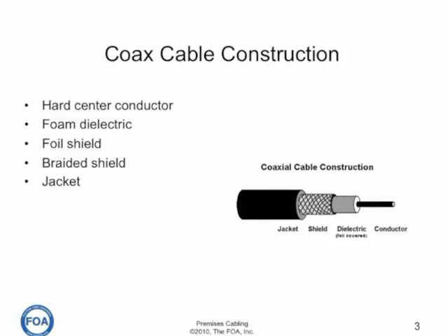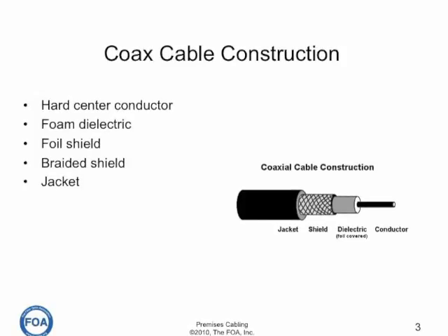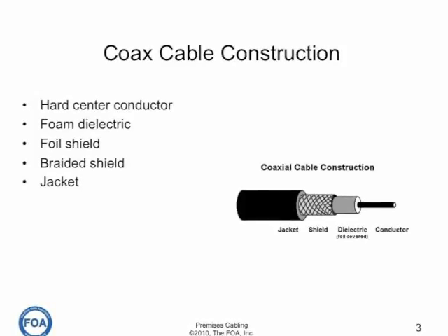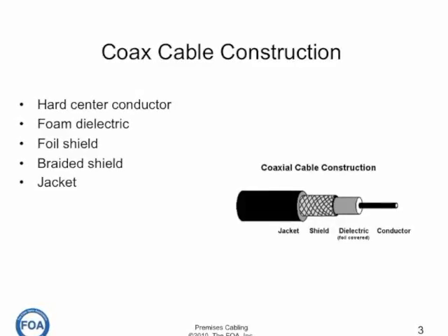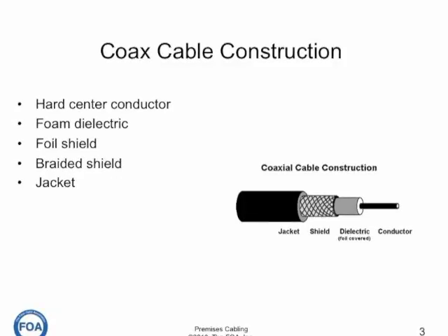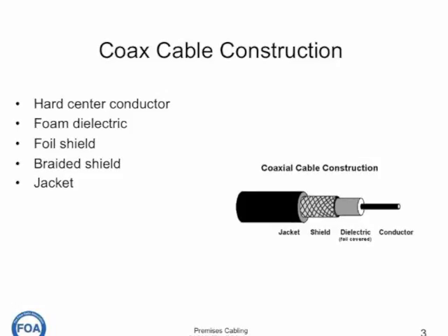The shielding is usually a combination of foil of some metal, usually aluminum, covered by a wire mesh, which is the outside conductor. The inner conductor is often stiff because it's used as a center pin, for example in type F connectors.